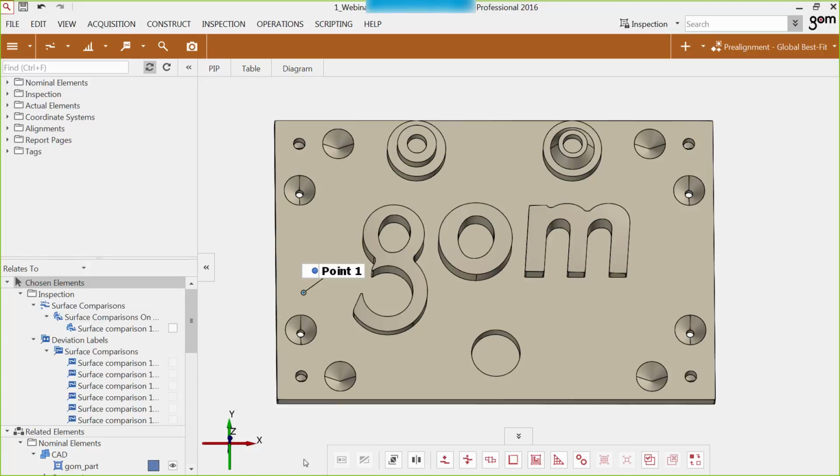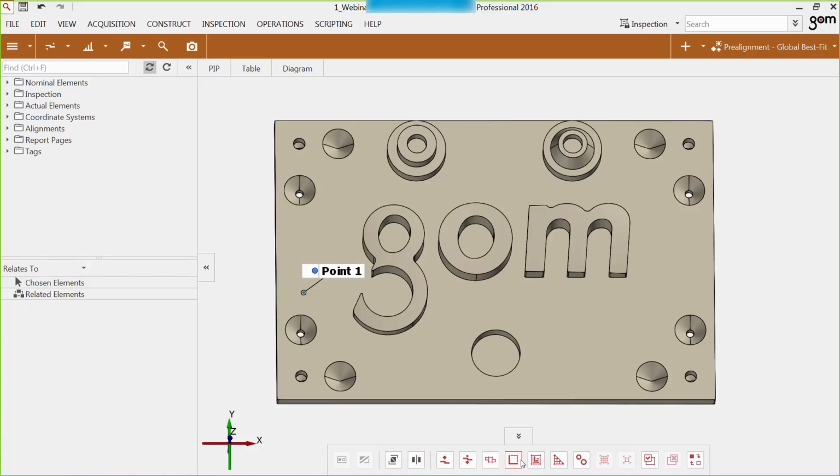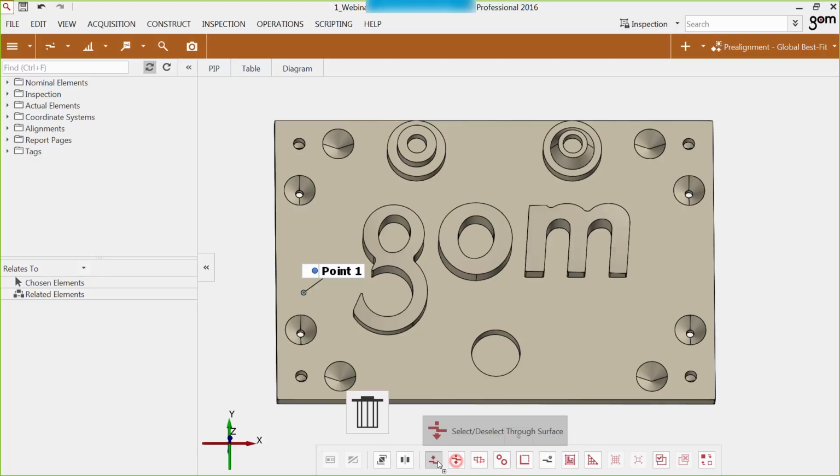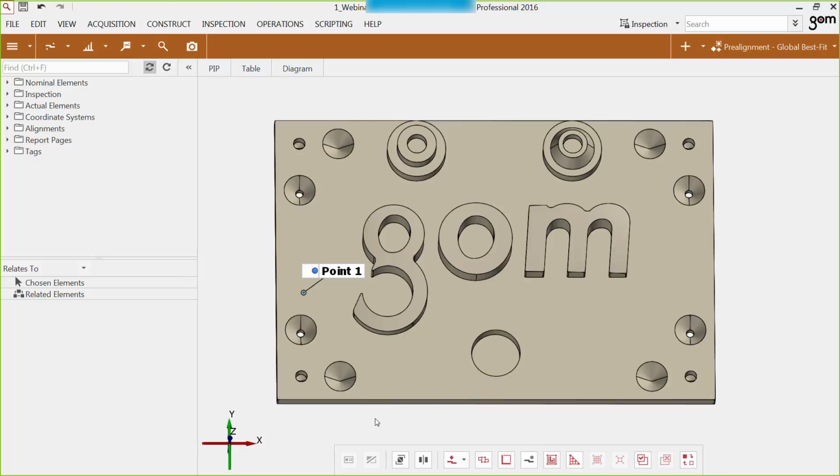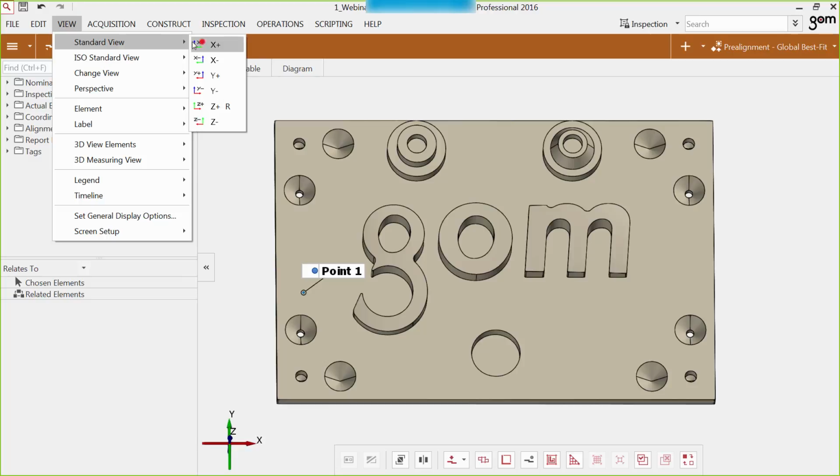In the default settings, the 3D toolbar includes the standard selection tools. Now you can add your favorite commands just by drag and drop. You can move existing items via drag and drop, and you can group commands. You can delete items with the floating trash bin. All showed options are also available for the title toolbar.